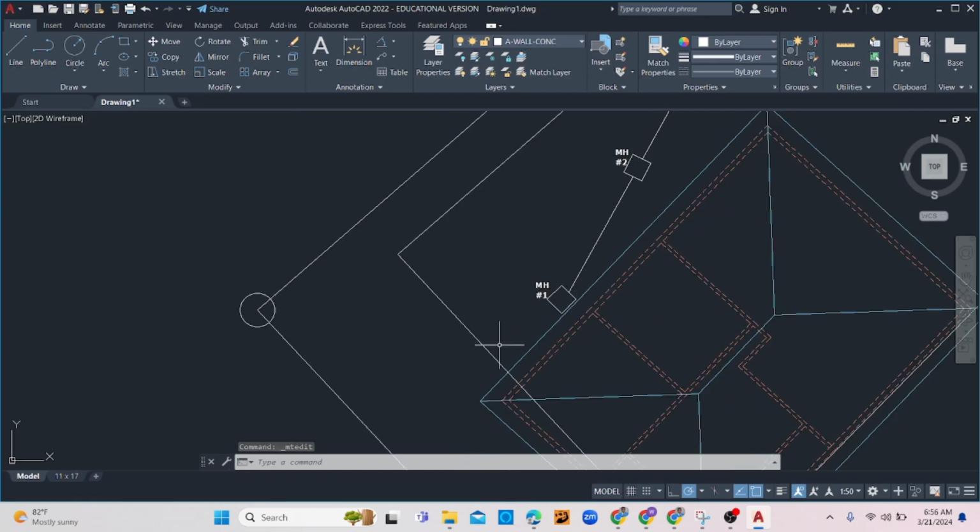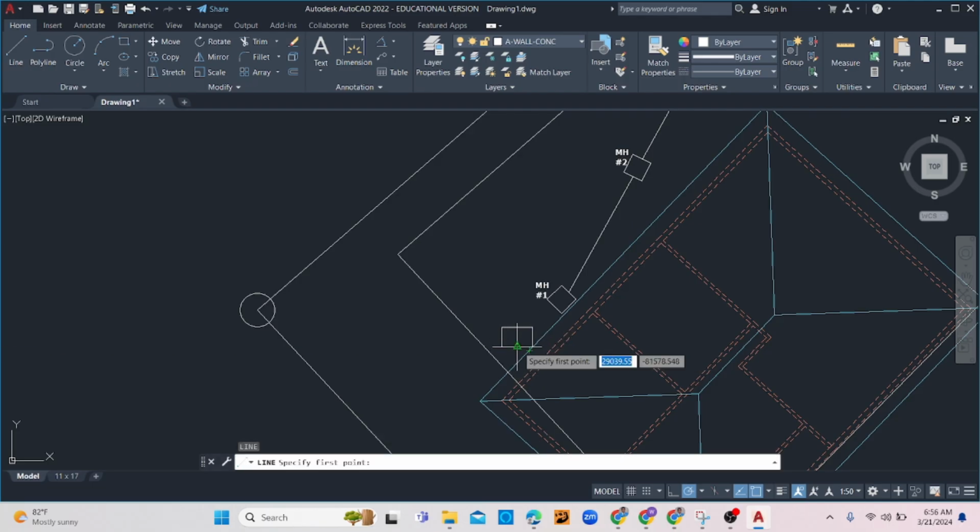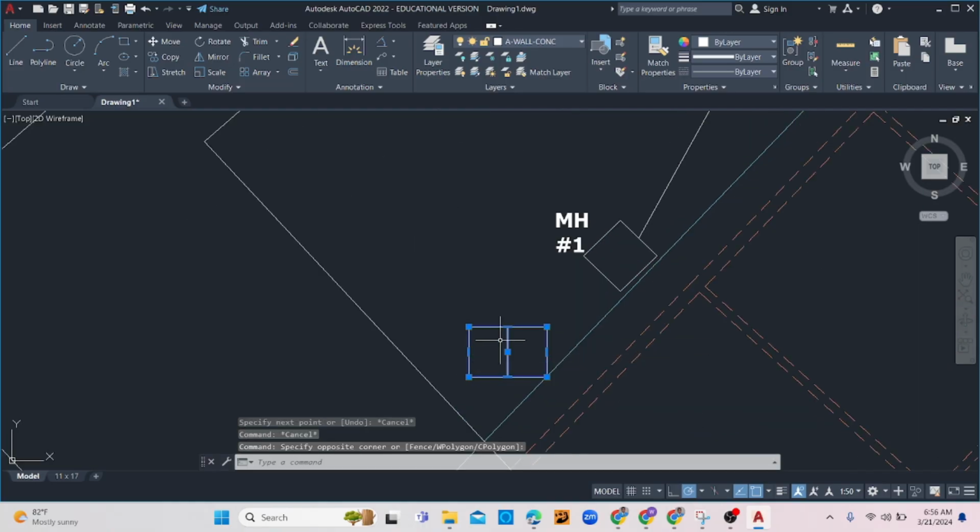Now you could also have other stuff, because since this is a kitchen, you could have a grease trap as well, so you could do another rectangle. For the measurement of the rectangle, you can make it 900 in width. Tab key, and we'll remain with the 600 millimeter height, or depth or width. Alright, just simply draw a line through the middle. We're going to be rotating it, RO, enter.